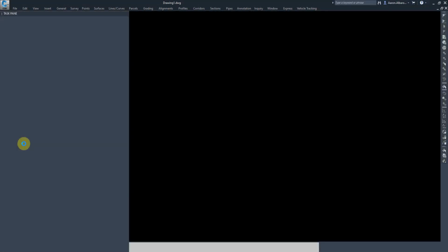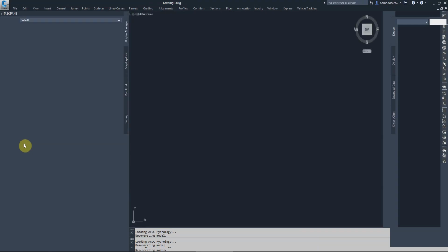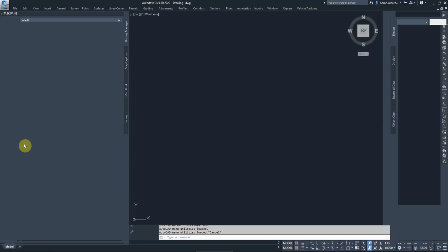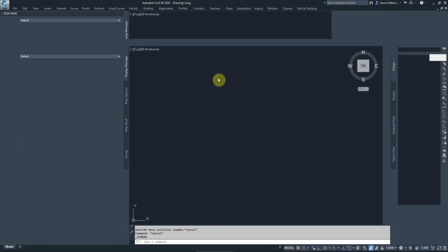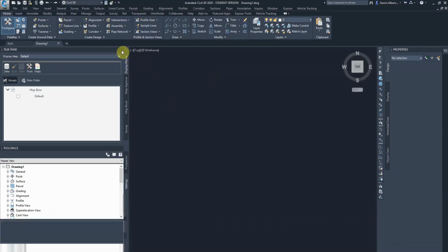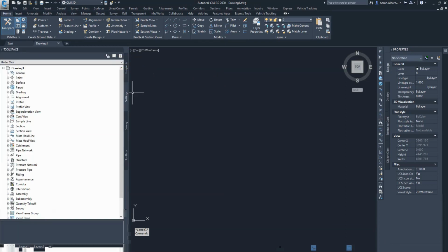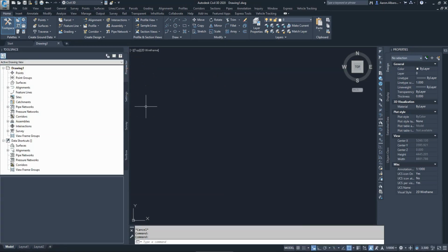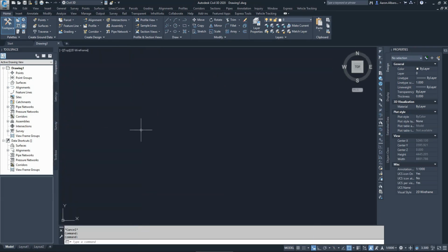We've got a few main settings that we have to fix first before we start doing any drawings. We have to make sure that we've got the right settings. Every time I'm opening Civil 3D, on purpose, I'm opening a new file. You don't have to do that. You can always open your existing file, and we agreed that you should fix the units on that file. I'm doing this again and again so I can make you very fluent and quick at fixing your units to start with. So as usual, the first thing we do is check our units.